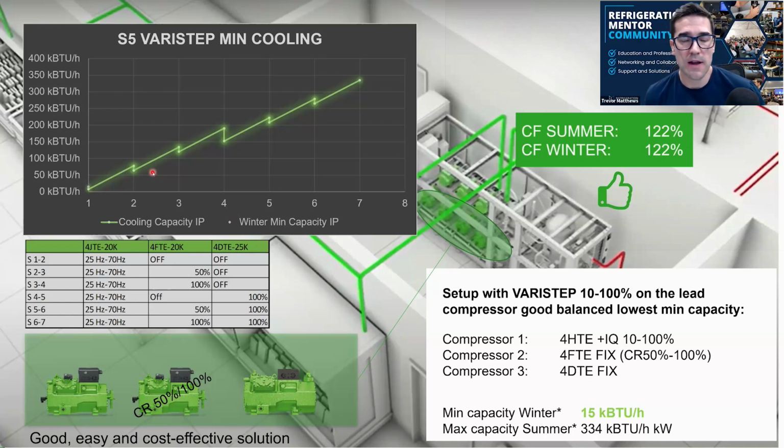Like you said earlier, if you have a big gap and it's real low load in the middle of winter, a compressor bangs on, bangs off, bangs on, bangs off. Then you get oil issues and lots of other not good quality of cooling. So, it definitely makes sense.